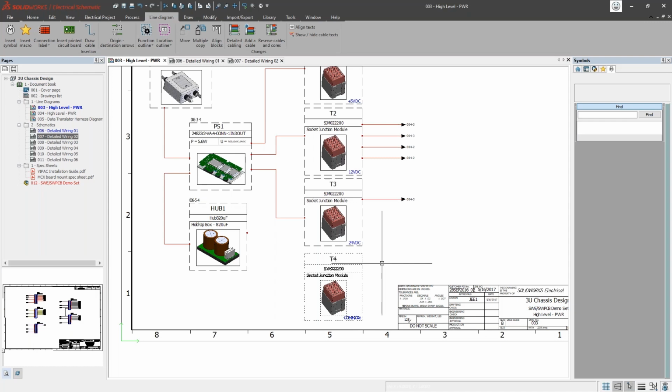You want to put a couple pins there, a couple pins on this sheet, so on and so forth. But you have to remember they're all tied to the same component, and using that Go To feature allows me to quickly go back and forth between all those different symbols throughout all the different sheets I might have in my project. In this case, I've got 10 sheets or so in my project, but some projects, some customers that I've worked with have 500 to 1,000 sheets in their project. So having that feature definitely helps find things a lot easier as you move through the